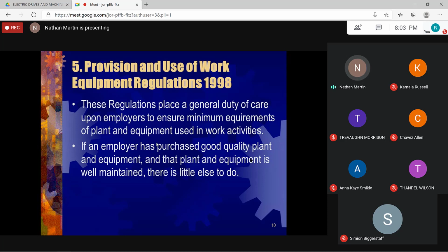For instance, if you're using an extension, anybody buy this extension downtown and you see them selling and them say cheap, you're probably using something or using a saw, something like that. You start to use the saw, the extension get hot and it burn up, right? Because the insulation is not good and it can't manage the current that it is pulling, but yet still they are selling an extension to do that type of work, right?